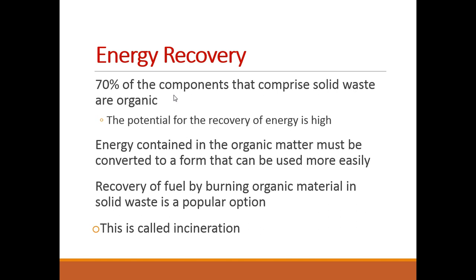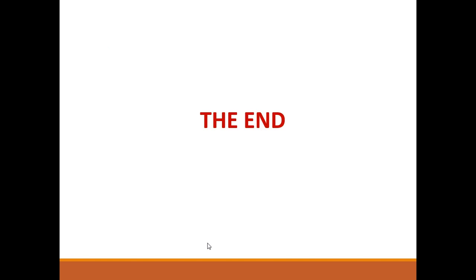The energy contained in the organic matter must be converted to a form that can be easily used, and that conversion process would be done by burning. So the recovery of fuel by burning the organic material in solid waste is a popular option, and this is what we call incineration. If you recall on that hierarchy pyramid of the preferred solid waste management strategies, incineration was listed just before landfills.